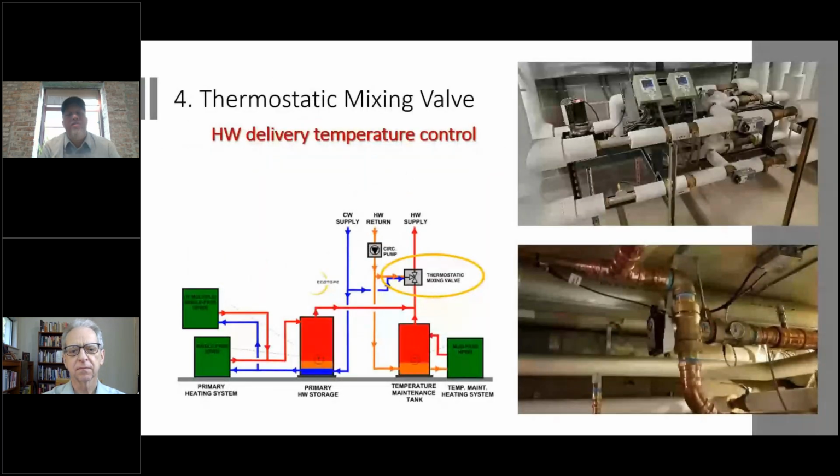And this is that fourth component, which is a thermostatic mixing valve. What we've found in our field work is that you really have to use these motorized mixing valves because the temperature maintenance tanks, which become the hot supply on these systems, vary a lot depending on the heat pump design and how it's set up. When you've got variation in the hot side, that can really screw up a mix if you don't have something that's dynamic and can feed back and adjust.